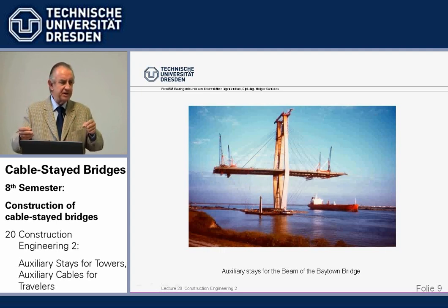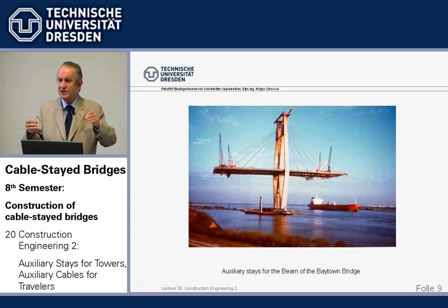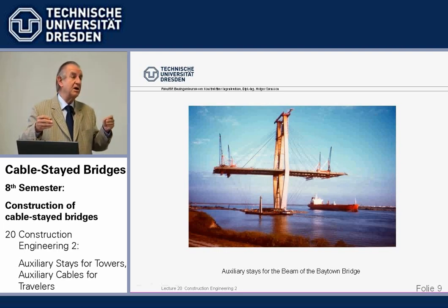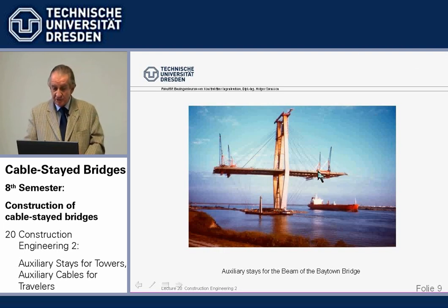It's clear, a bridge is much more vulnerable against high winds in the cantilever stage when it's not connected than in the final stage. We've done certain things in the final stage, but there the problem wasn't so critical. And there have been several hurricanes going over the bridge during its lifetime. One, 1996, I think we opened it. Did well. And here, to be sure, we used auxiliary tie downs, after we had a certain initial free cantilevering, tie downs to take care of the hurricane.